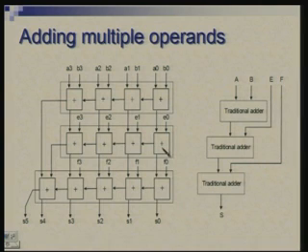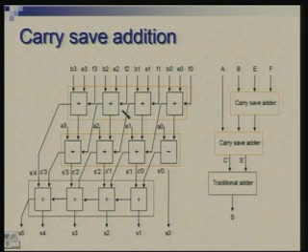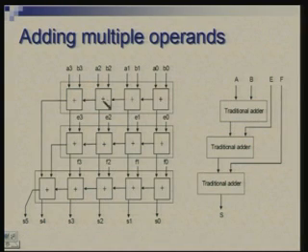So, that makes it 1, 2, 3, 4, 5, 6, 7, or if you go like this, 1, 2, I am sorry, 1, 2, 3, 4, 5, 6, 7. Whichever way you go, there is a chain of 7 adders. Okay. Now, in the last stage you have one extra adder here, where our numbers were 4 bits, because as you keep on adding, the magnitude keeps on increasing and you have to accommodate extra bits. So, these carries you do not throw away, let them be absorbed by an adder here.